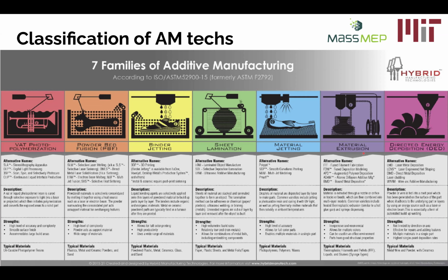And so if we think about tooling applications, and many of the examples that Mandy showed previously, like from Deutsche Bahn and others, where they have alignment jigs and fixtures and things like that, those are printed on extrusion machines because the part doesn't need to be perfectly strong. It's simply an alignment fixture. It's going to bear no load whatsoever, and I just want a tool that I can make quickly and inexpensively and deliver to the field. Conversely, when we look at, for example, those football helmets that Mandy talked about, we would never use material extrusion for an application like that, and that requires a little bit of process understanding.